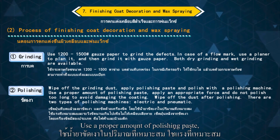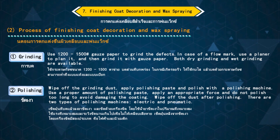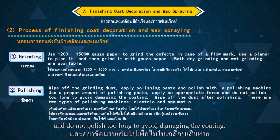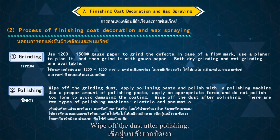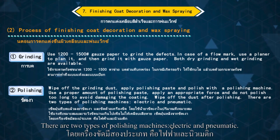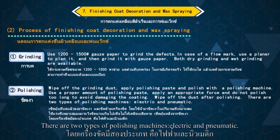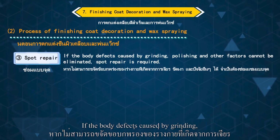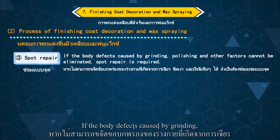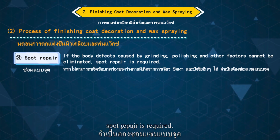Use a proper amount of polishing paste. Use an appropriate force, and do not polish too long to avoid damaging the coat. Wipe off the dust after polishing. There are 2 types of polishing machines, electric and pneumatic. 3. Spot repair. If the body defects caused by grinding, polishing, and other defects cannot be eliminated, spot repair is required.